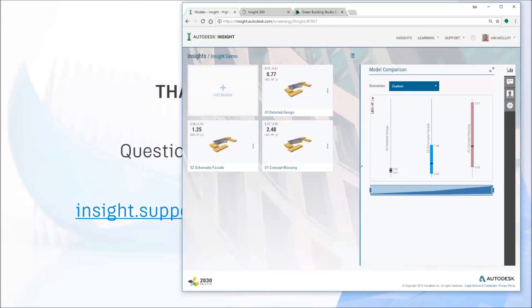If it's not showing up, but it's a small piece of wall, it could be the resolution, so you just need an increased resolution. But if it's not showing up, check if it's showing up as a surface type shade, because that means that there's some other gap in the model that means it's not being interpreted as an analytical surface type exterior wall.